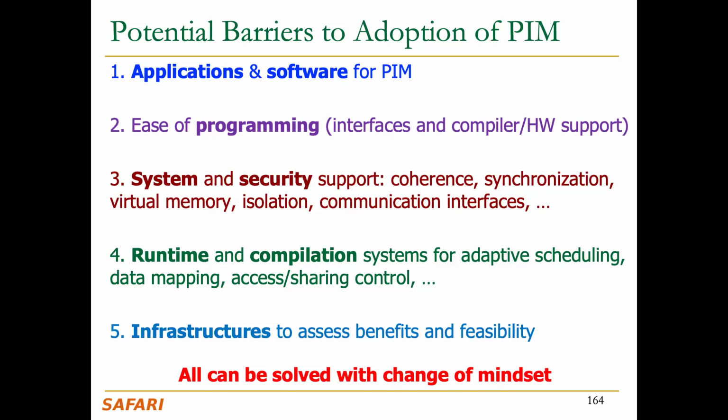Yes. And I actually blame the mindset for that, because this is such a simple thing. We actually test any DRAM chip. You violate the timing parameters, and you get this row clone operation. It's so easy to do. But unfortunately, this is the mindset issue. The industry has evolved in such a way that memory is memory, no computation. Leave the task of computation to the processor. So that's the reason I don't think it is commercialized.